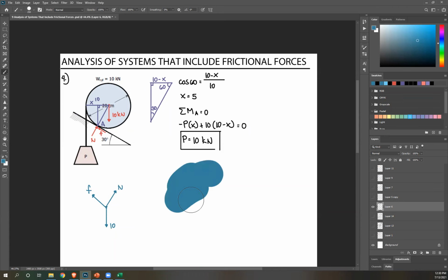And that means any force tangential to your pulley or cylinder will also act at its center. So that means we can analyze it this way. P is also acting at the center. Okay? So I'll place that here. Another downward force P, or we can just put it here. P.